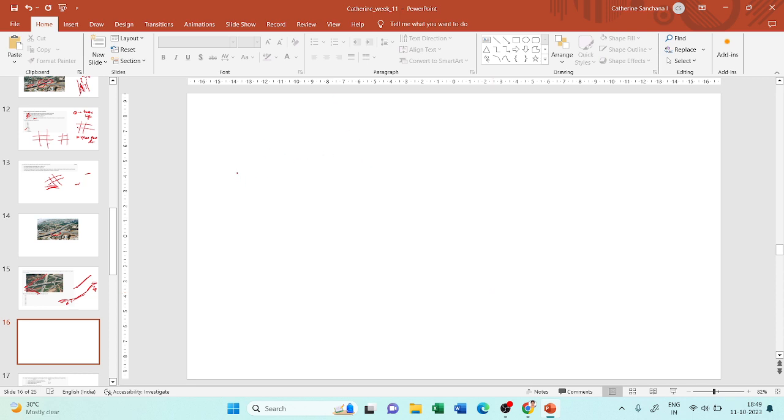So this is my ramp. Say here is my upper end and it has a summit curve, and this is my lower end and this is a valley curve. If you see the definition of the curve, you will understand why they call this a summit curve or this a valley curve. So what is the definition of a curve? What will your intuition say? If I'm traveling in this direction, then this part will be my summit curve and this part will be my valley curve, because here my vehicle is going up and here it will go down. So that will be your intuition.